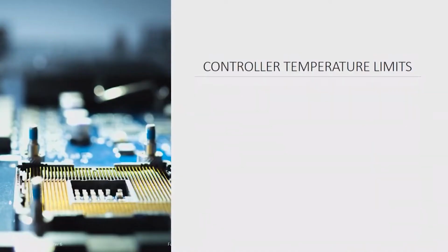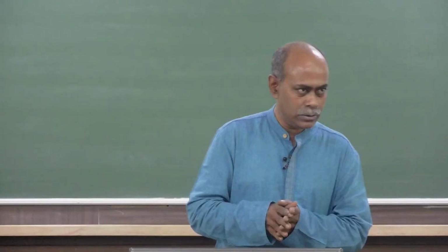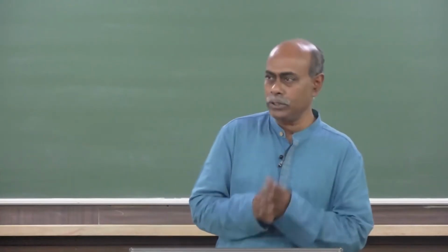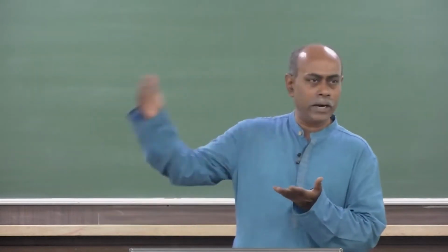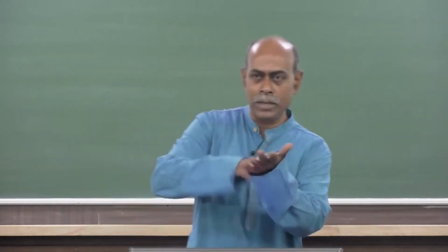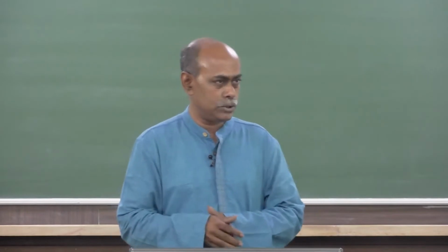So, the idea of this lecture is to give you a quick overview of what are the important thermal considerations in electronic design, in particular in power electronic design, because that is where thermal becomes a significant challenge, and how to address them. And these have to be done at the design stage when the circuit layout is being designed, when the components are being selected. It is not an add-on that after you finish all the design you slap on a fin and then put a fan and keep it cool, it is not like that.